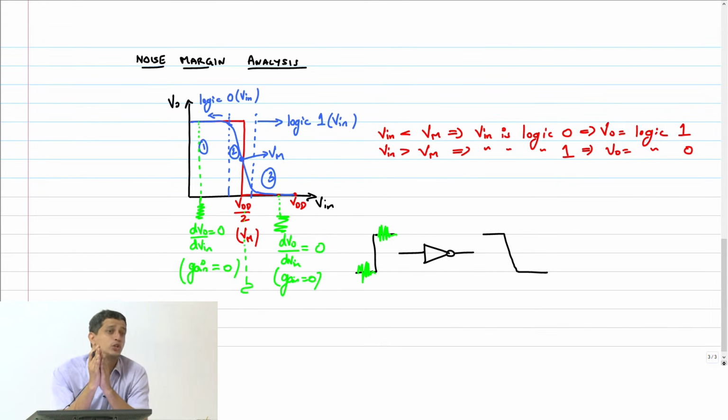It should actually be a vertical line. Gain should be infinity there. But since there is a deviation, it has a very large gain in this region, which means the output will actually get inverted and it will appear like this. Right? But of course, it can't be a perfect sinusoid like this, because as I move away, the gain is changing and all that. So effectively, it will be a distorted sine wave.